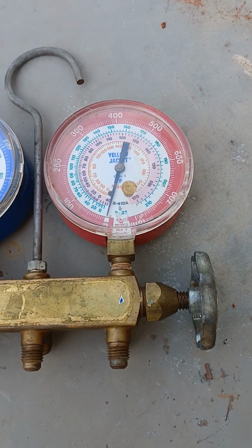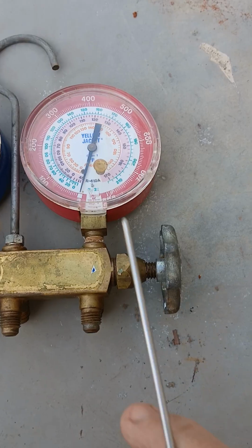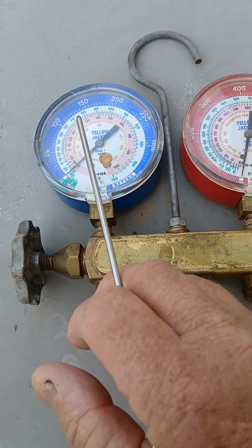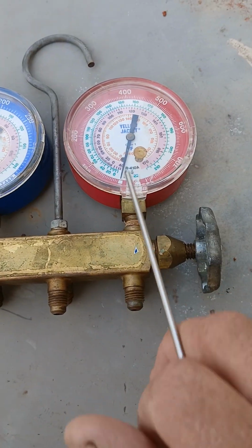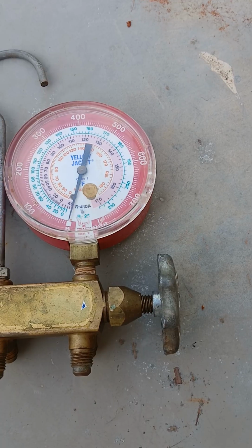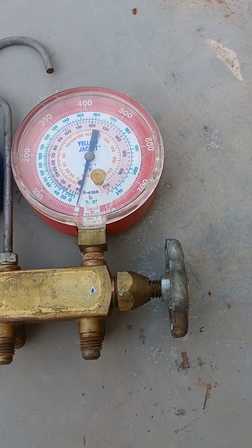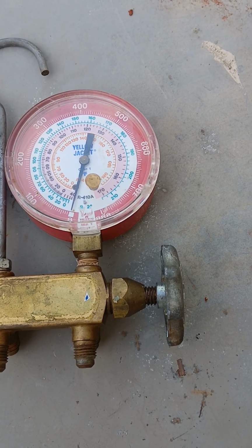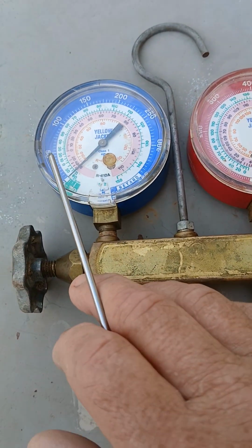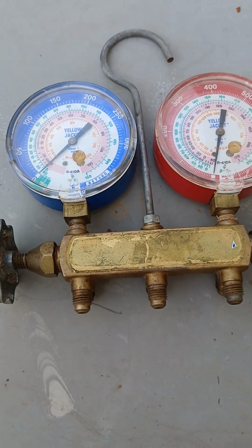So where does this leave you? You have two terms, superheat and subcooling. Subcooling would be measured on the high pressure side. The low pressure side may be the blue side, and the high pressure side the red. You can just think of red as being high pressure, hot, and blue being low pressure and cold.